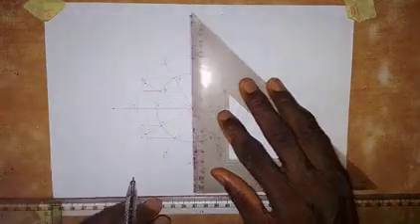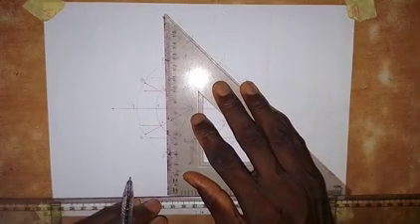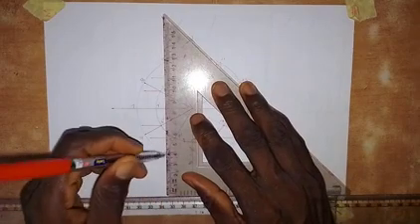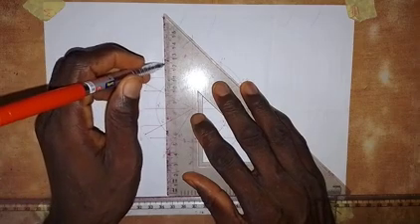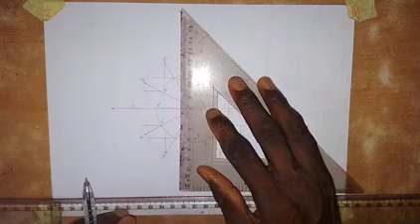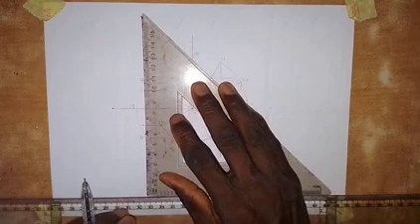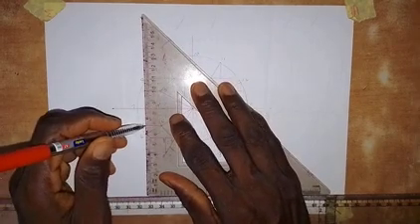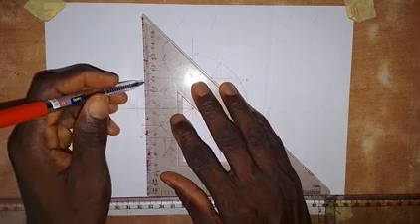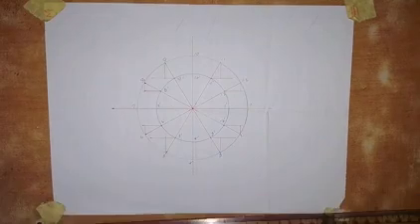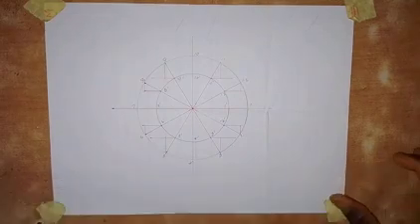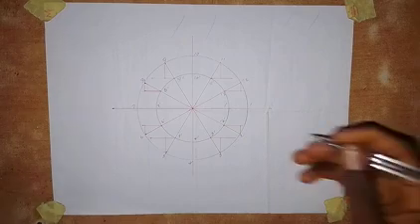down. Then coming to this side, from 5 I will draw a vertical line up to touch the horizontal line, and from 9 I will draw a vertical line to touch the horizontal line. Then from 6, we draw a vertical line to touch the horizontal line. From 8, we draw a vertical line to touch the horizontal line. So we have this point. So these are the points that we are going to join together to have the ellipse in place.